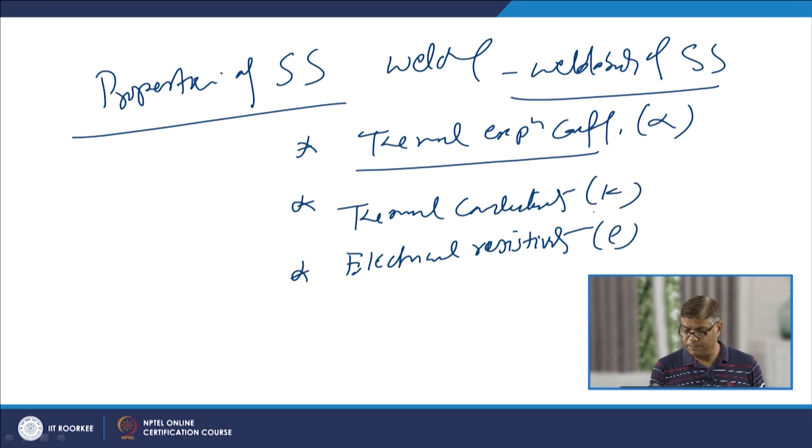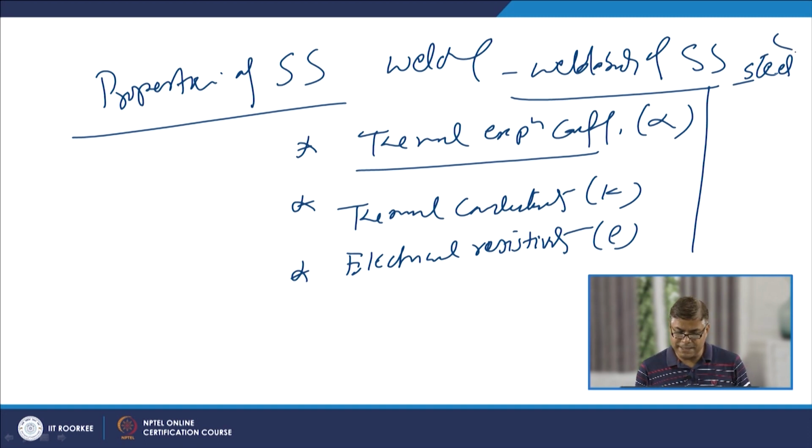In general, if we compare these with carbon steels, for the stainless steel the thermal expansion coefficient is extremely high, thermal conductivity is very low, and electrical resistivity is also high.